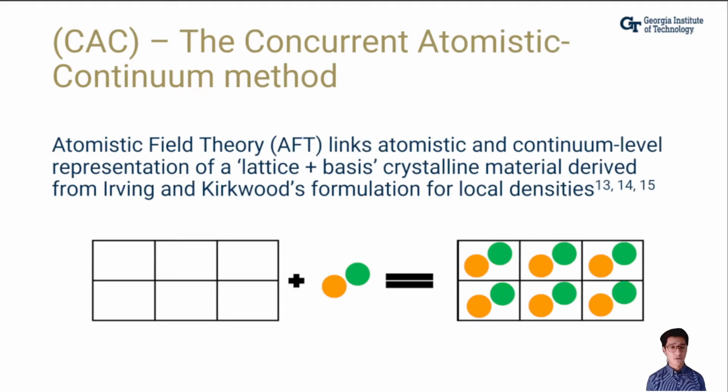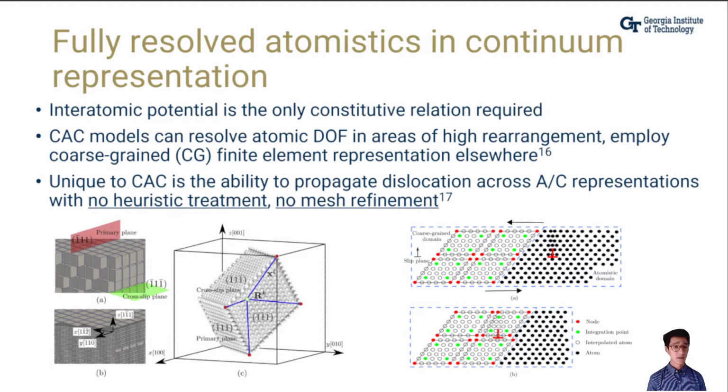We've recently shown, however, that the application of CAC, the concurrent atomistic continuum method, to this problem domain is a promising choice. The foundation of CAC is atomistic field theory, which links atomistic continuum level representations of a material based on Irving and Kirkwood's formulation for local densities, in a simultaneous lattice plus basis representation of a crystalline material. In CAC, the only constitutive relation required is the interatomic potential.